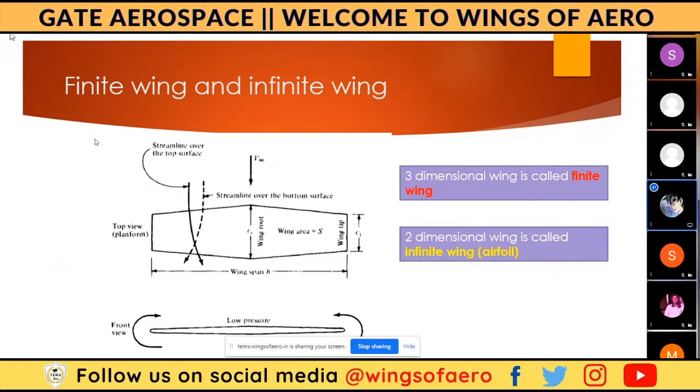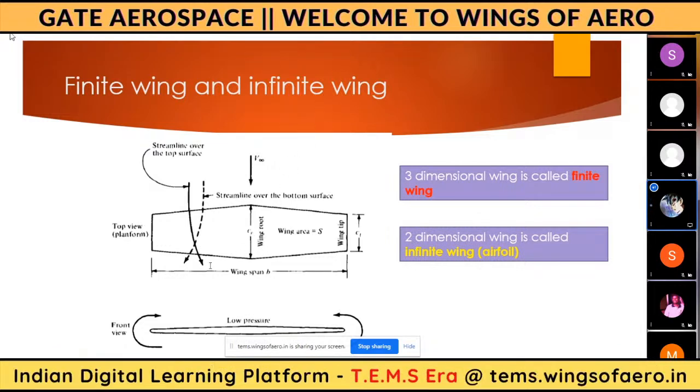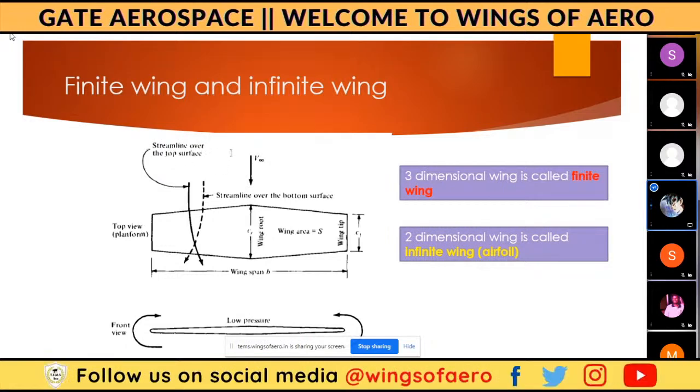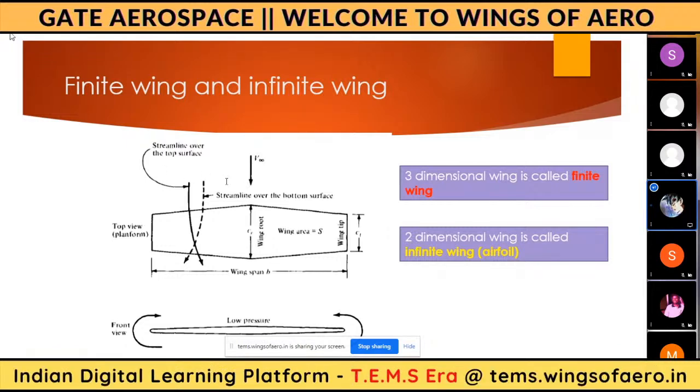Over the surface of the aerofoil, there is an induced flow. On the top surface we will have low pressure, and on the bottom surface we will have high pressure. Because of the pressure difference, we get some lift. As per circulation, when it is at rest the circulation is 0. When it is in motion, the circulation begins. There will be circulation around the aerofoil, and because of the circulation we get some amount of lift.